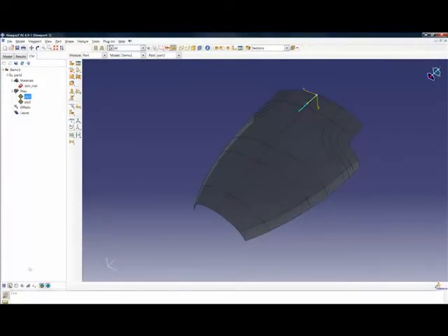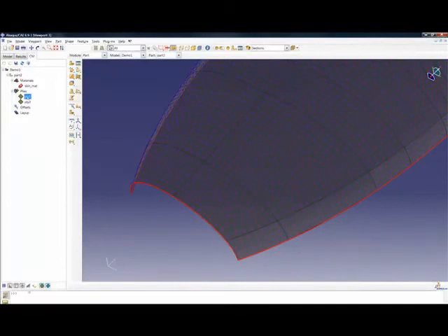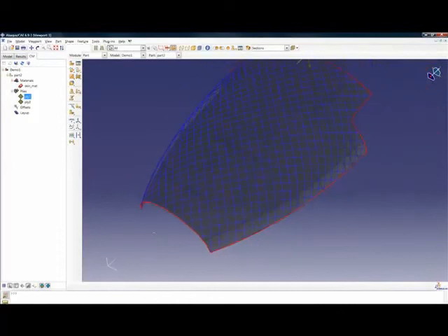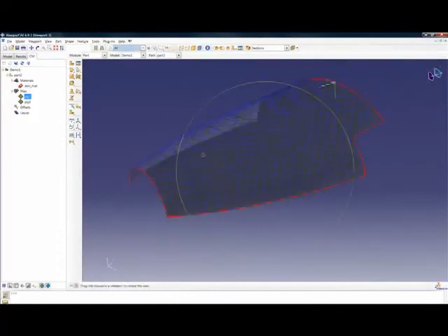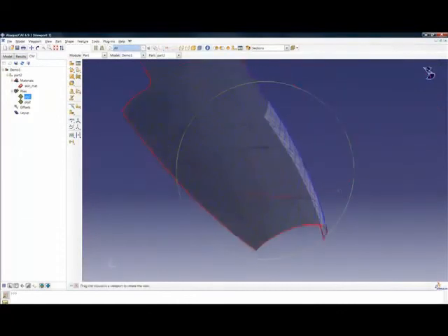The next button shows the application direction and the reference angle. Then we have the ply boundaries, and now you can see on the individual elements the fibre directions are shown. If we zoom in a little bit closer, you can see the effects of the curvature. So we switch between the 45, and we can now see that the fibre angles are clearly illustrated.